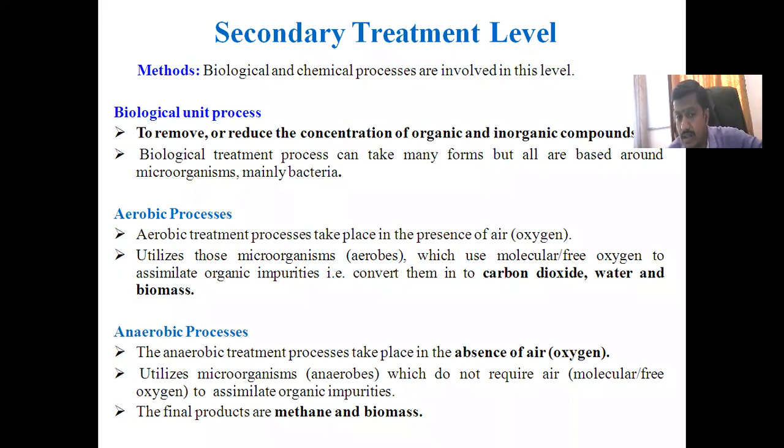How does it work? It utilizes those microorganisms which are present in that wastewater. We call them aerobes. This process utilizes microorganisms which use molecular or free oxygen to assimilate the organic impurities.